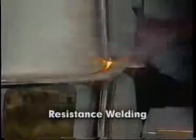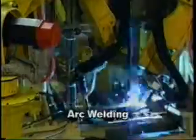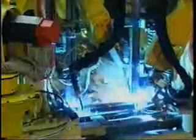resistance welding, laser beam welding, and electron beam welding. Arc welding processes use an electric arc as the heat source to melt and join the base metals. The arc is struck between the workpieces and the tip of an electrode.